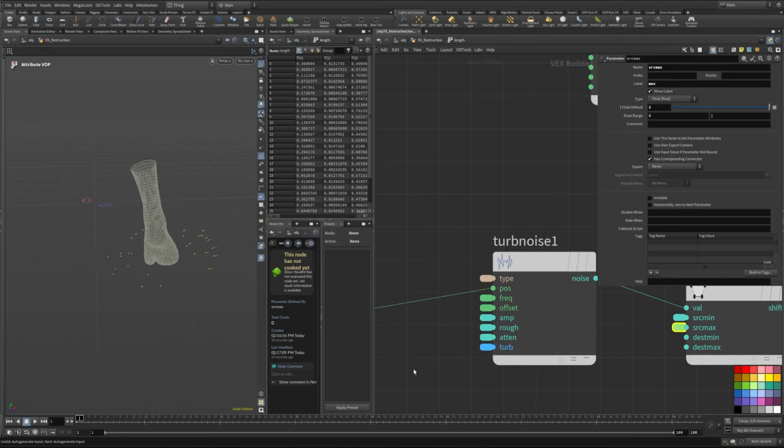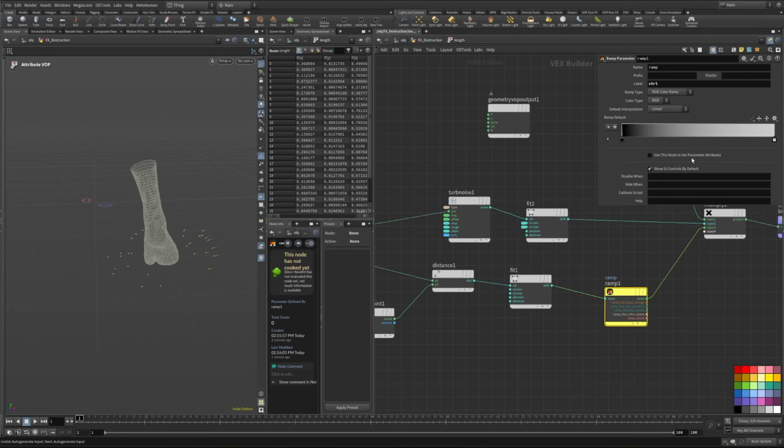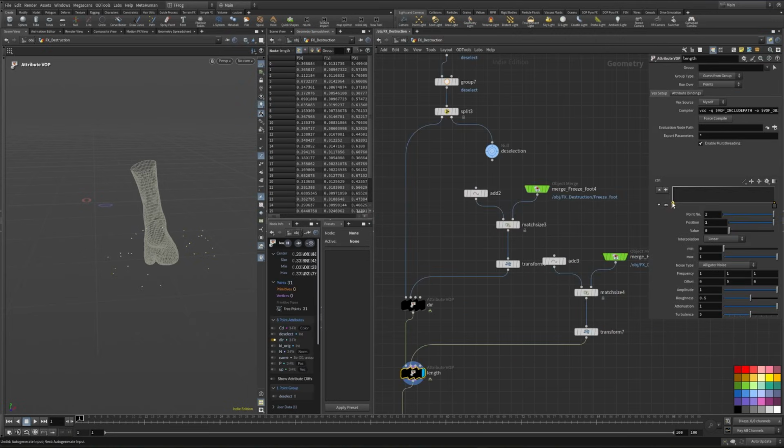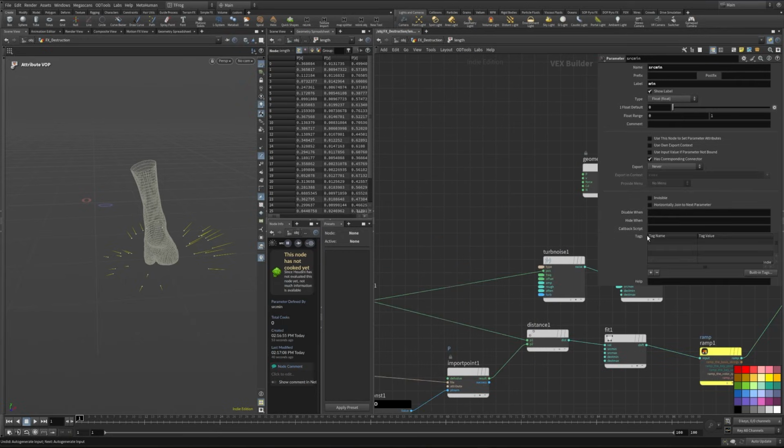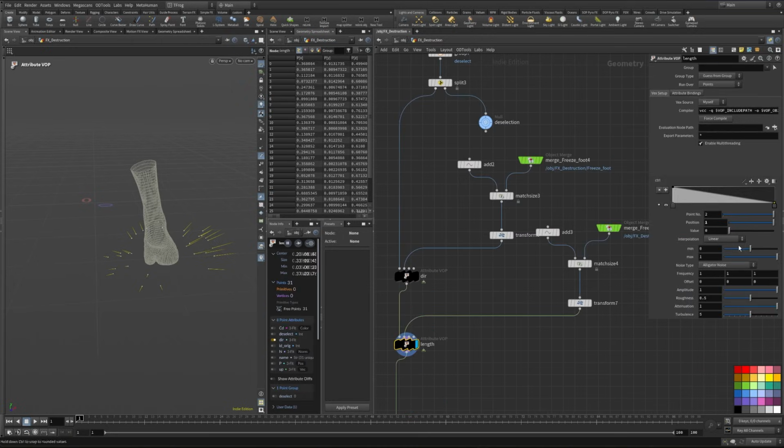Let's go up. And I thought I changed it to a spline ramp, like so. And the first part here goes up, like this. For the min and max, I will also maybe change some values here. So I go inside and change the min to -1, so I have control over the min to also go into the minus direction. And for the max, I will also decrease it a little bit to maybe around 0.7.